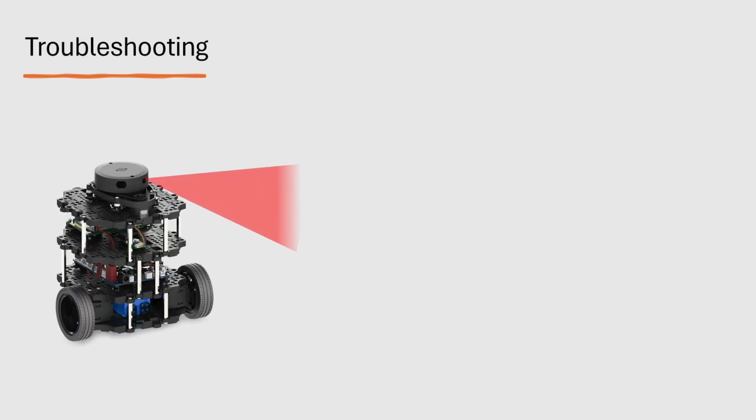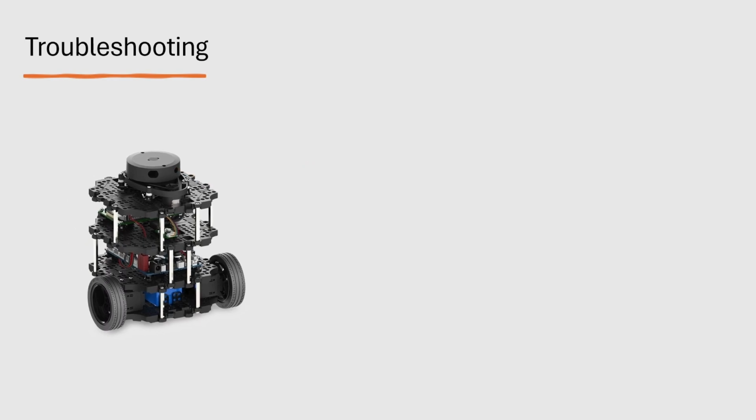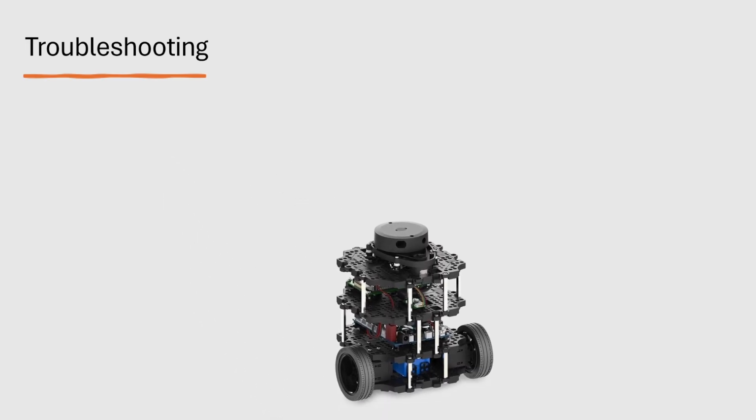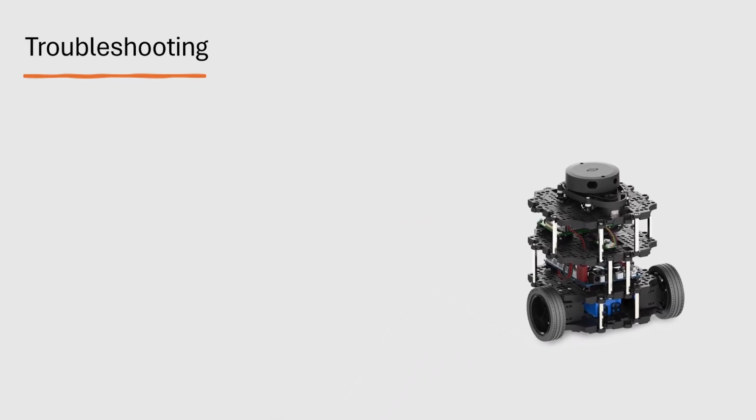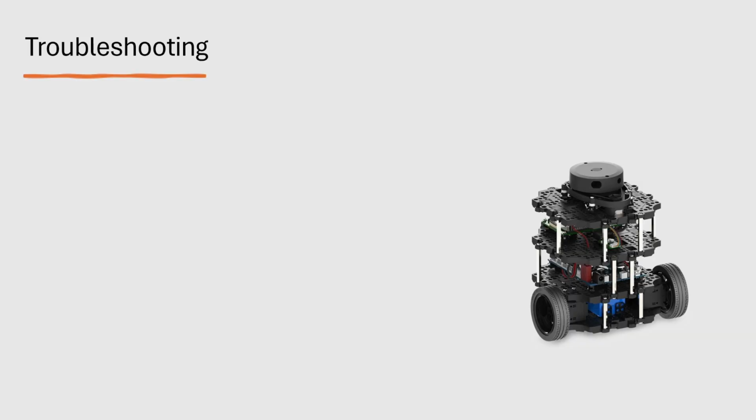For example, we used ROS tools to check that the LiDAR was sending scan data at the correct rate and that wheel motion was responding accurately to commands. If something did not respond, this stage gave us the opportunity to troubleshoot wiring, firmware installation, or incorrect configuration settings. Successfully completing this task confirmed that the robot was fully functional in a standalone configuration.